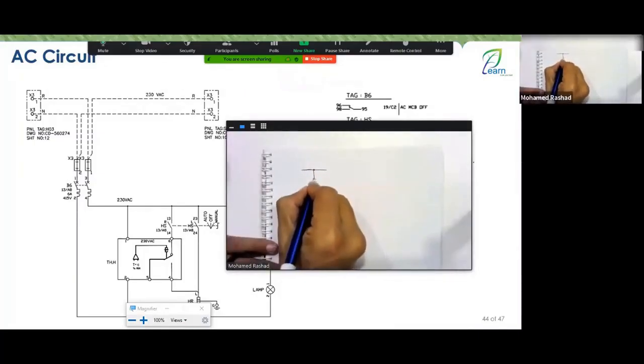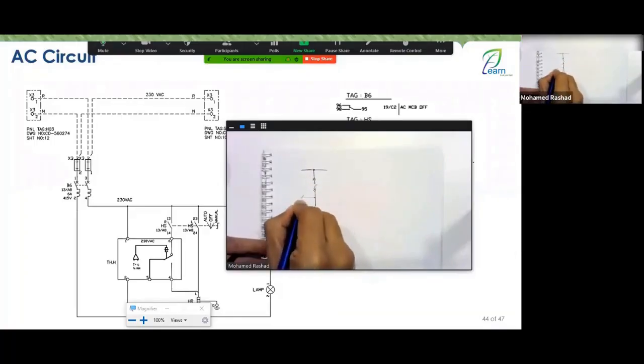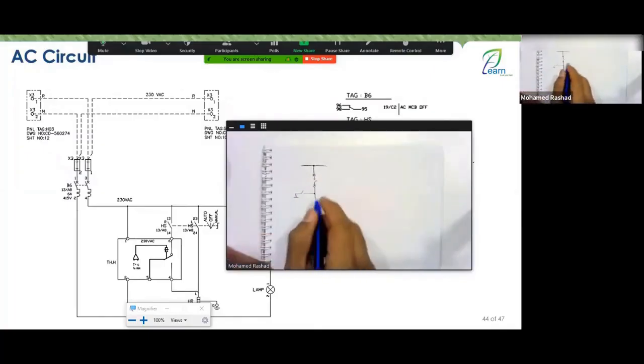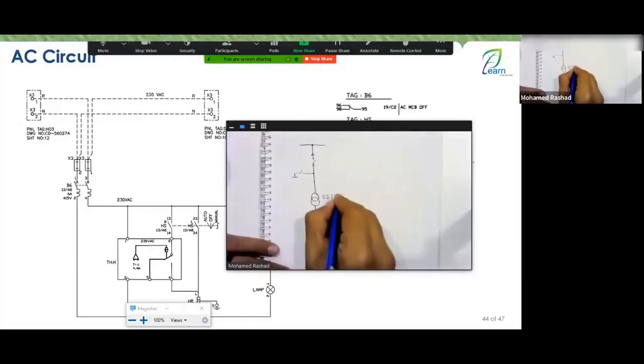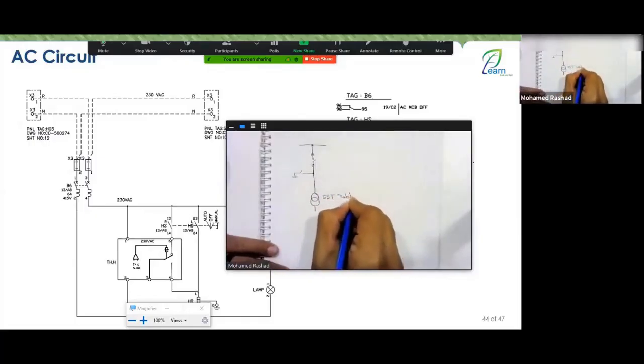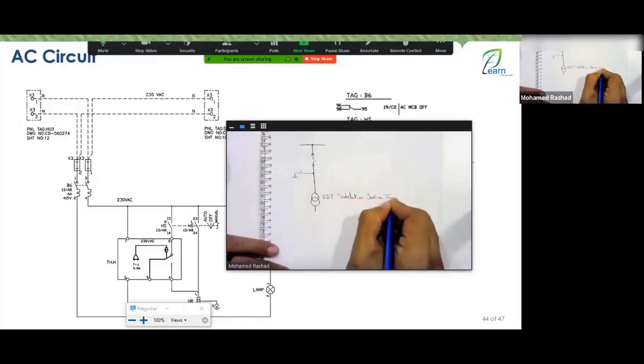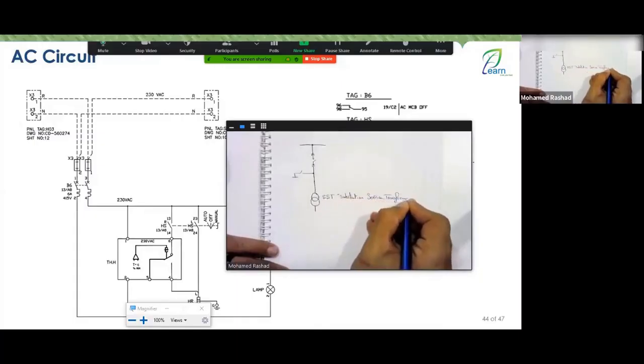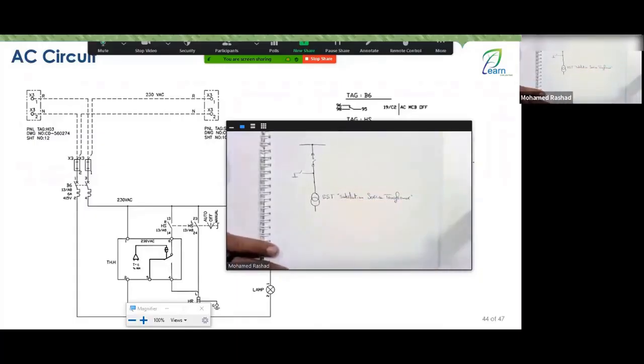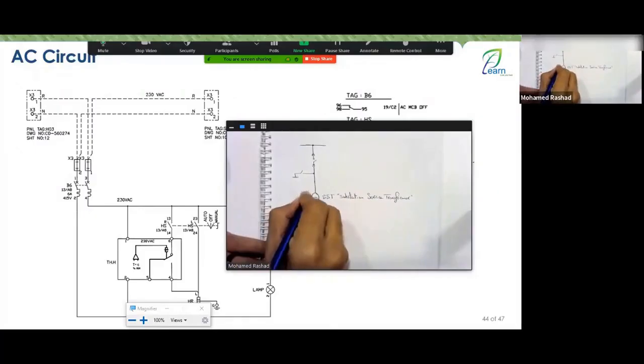Of course, through the withdrawable circuit breaker that we discussed previously, it exits from this point. In this setup, you have the feeder air switch. One of these feeders exits here to something called the substation service transformer, the SST, which stands for the substation service transformer. This is the transformer that supplies the station services. It steps down from 13.8 kilovolts to give you 380 volts on the other side.